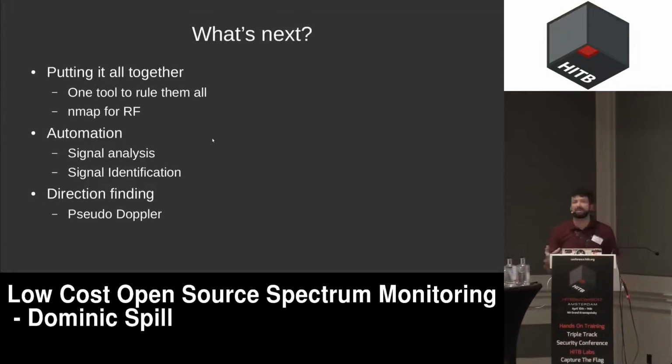So the idea there is we can visually pick out packets and data transmission types and look at what kind of radios might be transmitting, and you can get a fairly good idea for what's transmitting, what type of device it is, from the type of radio connection it uses. Quite often there's an awful lot of low power things that will use 2FSK in ISM bands. If you go and look at the appropriate bands, you'll see things like GSM and so on and so forth.